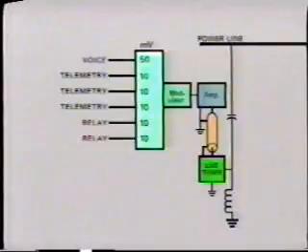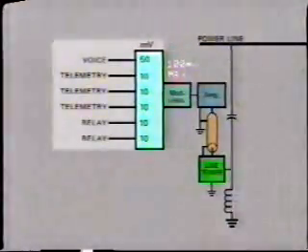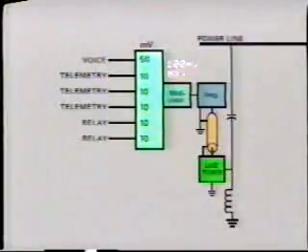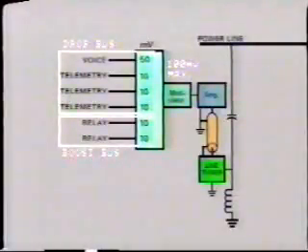We can increase the modulator output voltage only so much, say 100 millivolts, before we run into the problem of overmodulation, where the final amplifier starts distorting. So typically the voice signal would be assigned, say, 50 millivolts, with 10 millivolts each for the remaining 5 tones. The voice and telemetry inputs are connected to the drop bus, while the relay signals are connected to the boost bus.